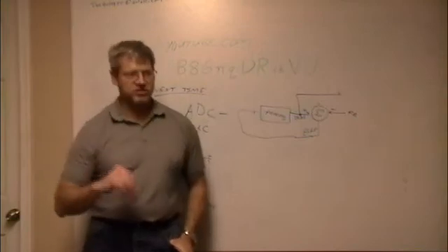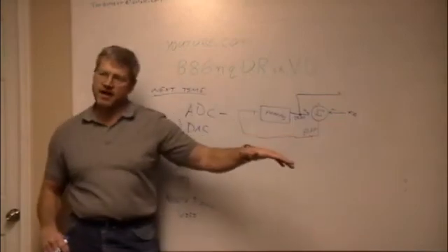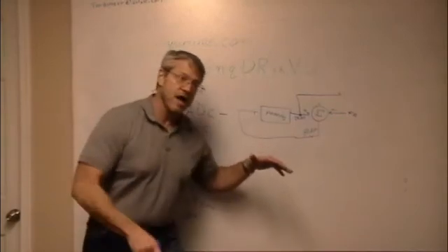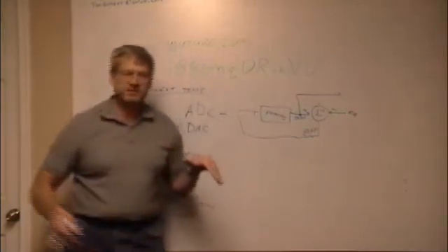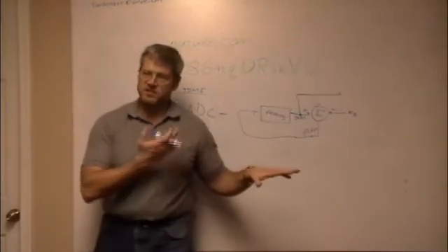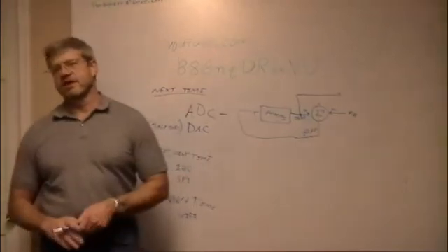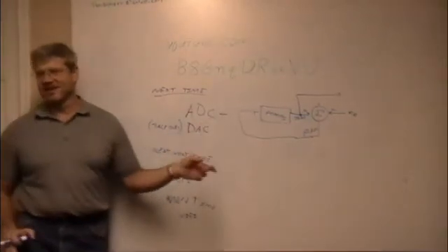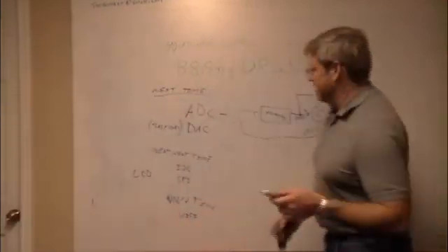A small change does a lot. So you've got the integral trying to smooth it all out, and at the same time you see, oh, but we're going the wrong way. It's going to get colder and it's going to get cold fast. And it says, well, okay, I'll start turning it back on, but I won't turn it on as hard because this thing's smoothing me out. And the process controllers build all that into them. Yeah. And you can spend a lot of time building one of these and getting it right. Right. But that said,